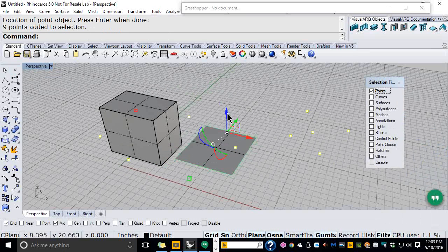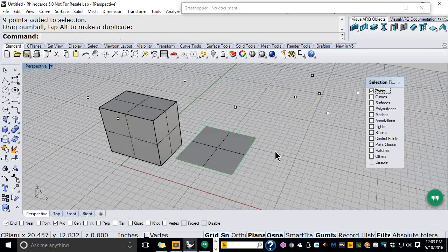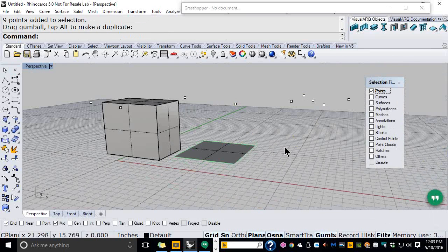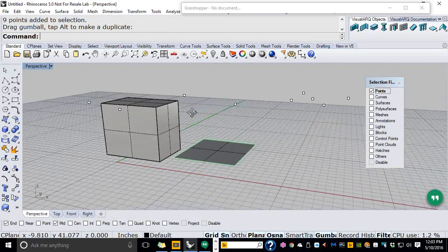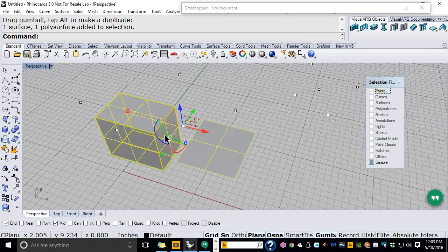Beautiful. Let's say I want to move them up here. I am really happy, and I continue working, and I send the information back from Grasshopper to Rhino, and I come to Rhino, and I cannot select anything. Notice? And almost every day I go, oh my God, yes, I forgot to disable the filters. So now I am able to select.